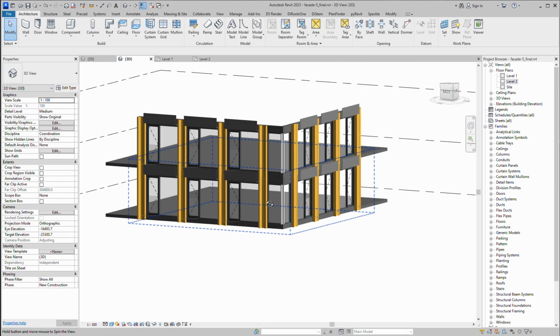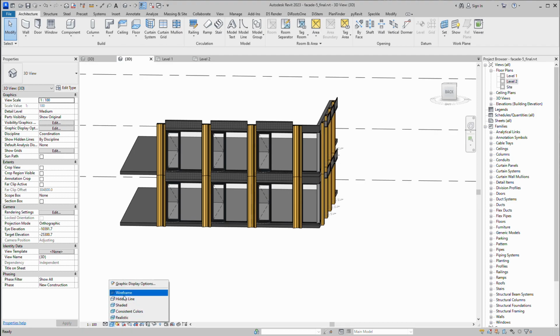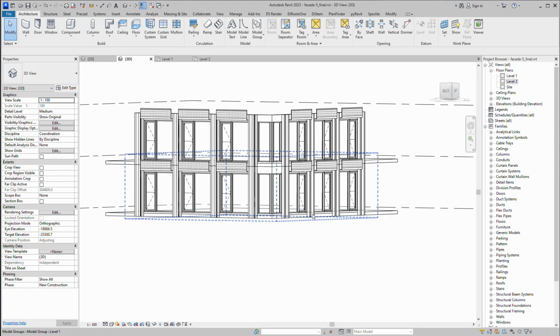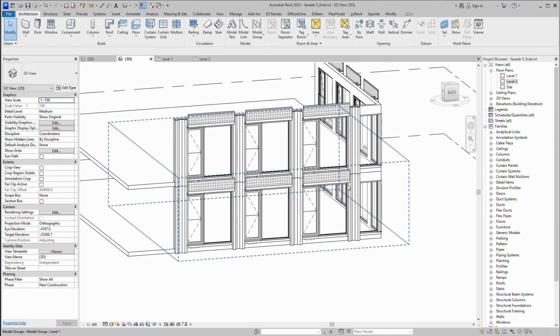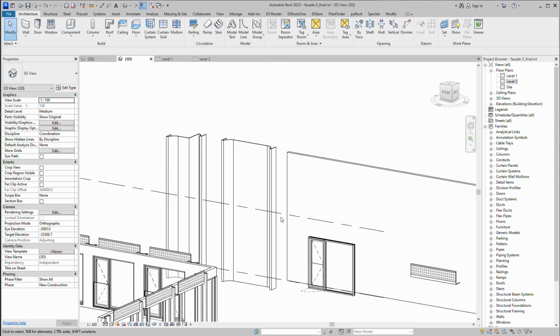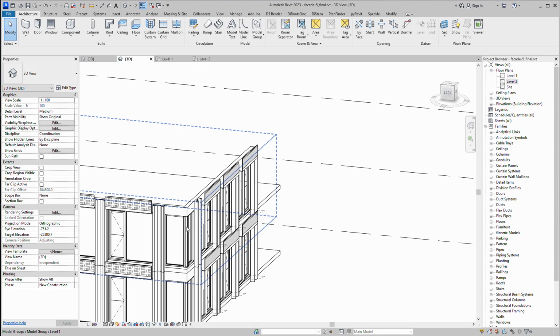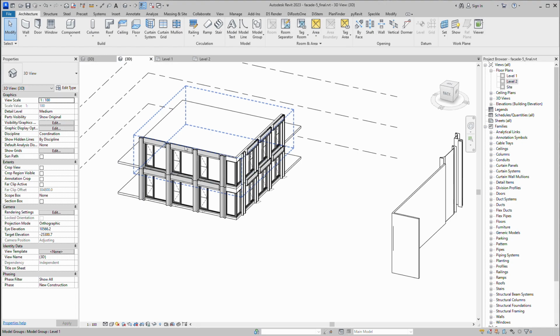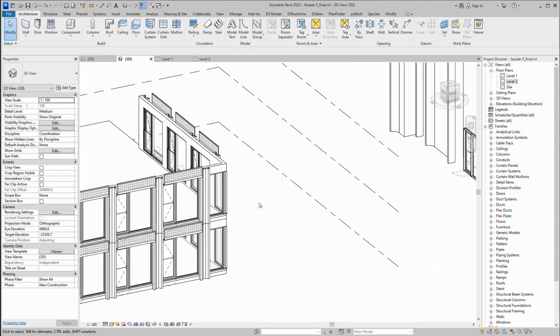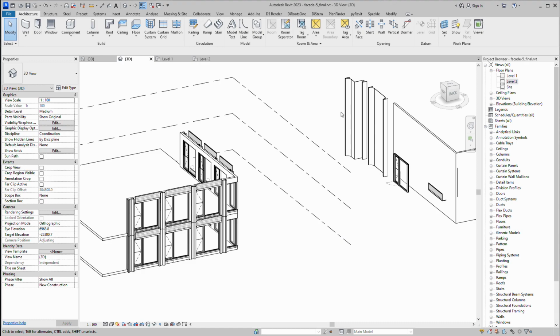And everywhere, I think everywhere. So as you can see, we're not spending a lot of time to achieve this facade. It looks much more interesting now, but we don't use any harder families. Even here I have, for example, the corner one, but instead of this corner one I created the corner window here, but you can use, for example, this corner one. And let's make this your homework. Just use or create your own pillars from the walls, and play around with that result, and leave some comments below my video. Just tell me how it's working.